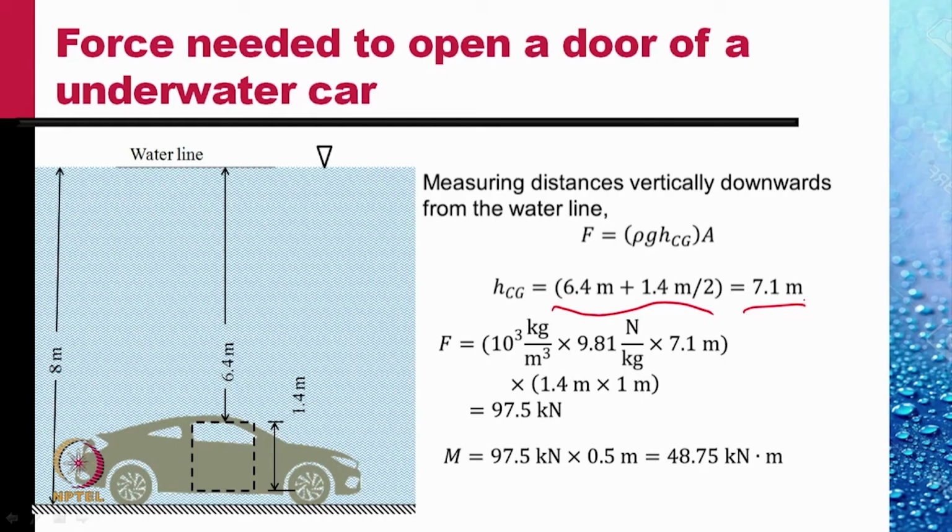The moment he would need to apply would be this force into 0.5 meters, if he applies a force at the middle of the door, which is 48.75 kilonewton meter. This is far beyond the capability of a human being. So, if this is a situation that exists, the driver cannot get out, cannot open the door.